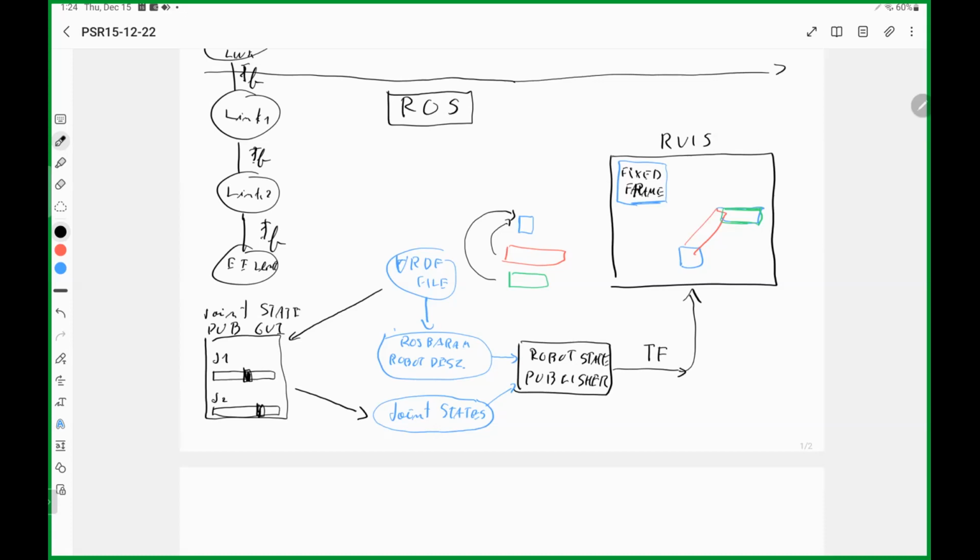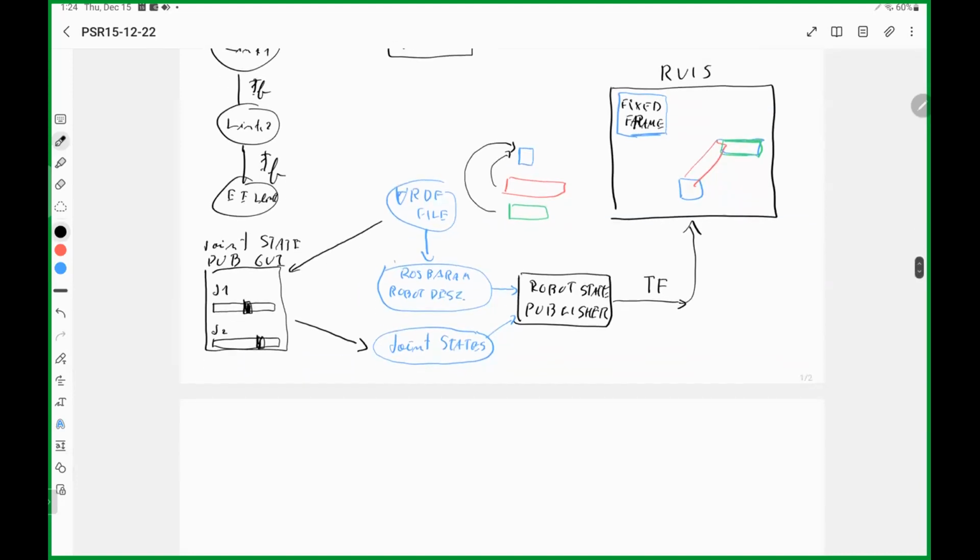Yeah, the GUI is something that will let you define the value. If it was a real robot controller, you wouldn't define the value, you would just be reading it. By another control loop, with which you will tell the controller, okay, now move. But it's a different control loop. One of them is just reading the position and feeding it to the joint states, which then goes into the robot state publisher. This is just unidirectional. Then there is another control loop, yeah, to move.